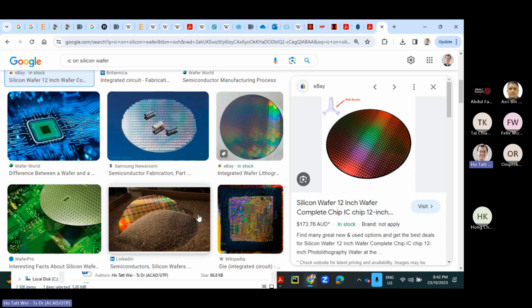When I talk about 157 or 183 nanometers of light, this is roughly half the size of the minimum, the smallest dimension that you can etch with light. So nowadays you see I have 157, that's the wavelength of my light. But how am I able to create features on the size of 3 nanometers when my light is only on the size of 100-something nanometers? That's because they play a lot of fancy tricks using interference patterns with the light. This is called diffraction patterns. They have some fancy patterns where they are able to mathematically create smaller patterns due to certain tricks they play with the light.